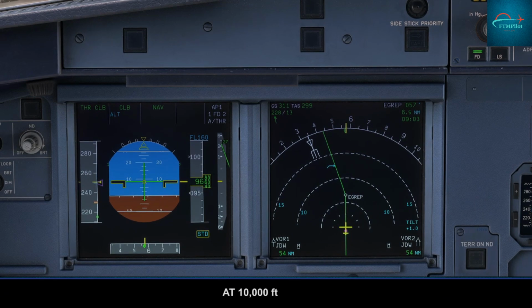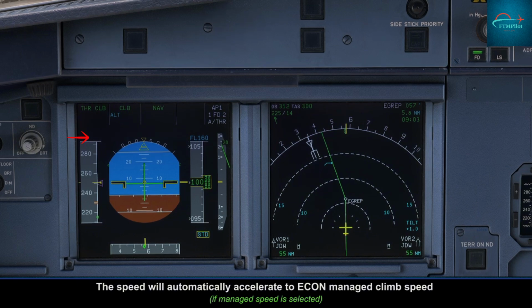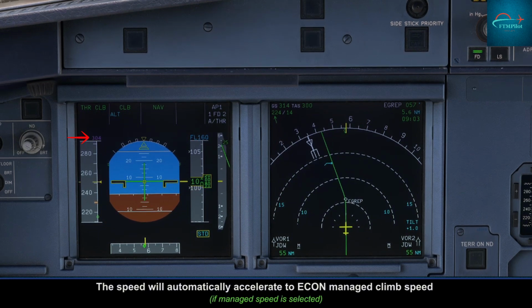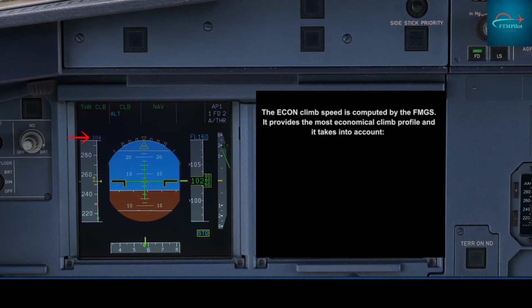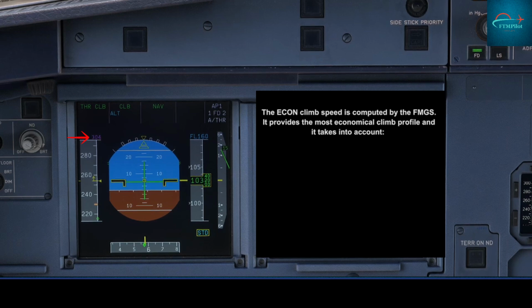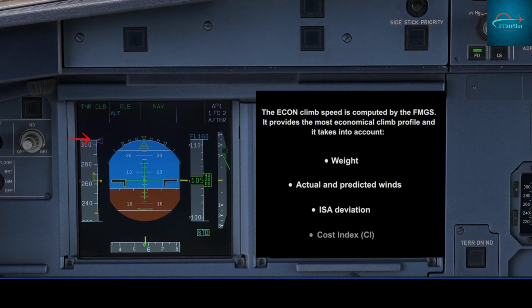At 10,000 feet, the speed will automatically accelerate to economy managed climb speed. The economy climb speed is computed by the FMGS. It provides the most economical climb profile and it takes into account weight, actual and predicted winds, ISA deviation, cost index.